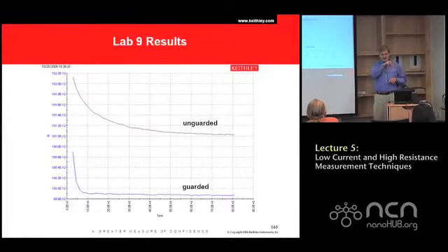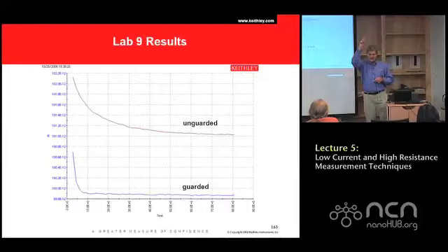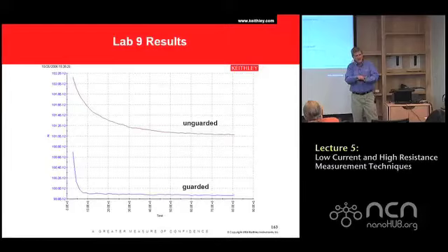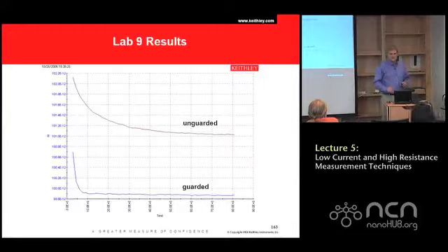And what I expect to see is at 0 volts, I see the leakage current of the system. That's the internally generated currents. When I step to 10 volts, I immediately see a lot of current, and then it starts to come down. That's the RC time constant of the system. And when the system reaches the end of the RC time constant, hopefully 100 points is enough, the delta between that and where I started is the leakage current of the system. So I get the offset current, the RC time constant, and the leakage current of the system. The step function test is a great test for testing the efficiency of your system and for characterizing your system.